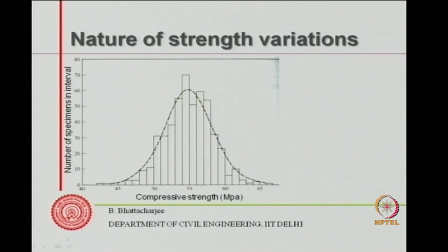Now let's understand the procedure. To understand the procedure, the first thing I must understand is the nature of variation of concrete strength. Supposing I have a concrete strength, I thought the mean strength would be somewhere, let us say, at 28 days age I am talking of, at the moment, I decided that it should have some kind of a mean strength of, let us say, 55 or so. This should be valid for any other mean strength also.